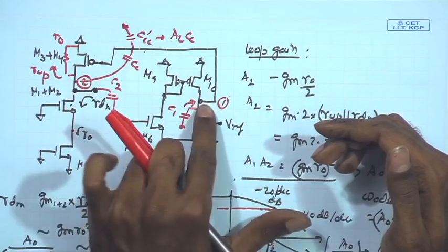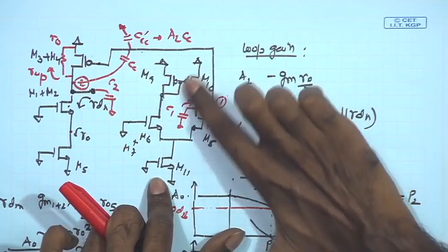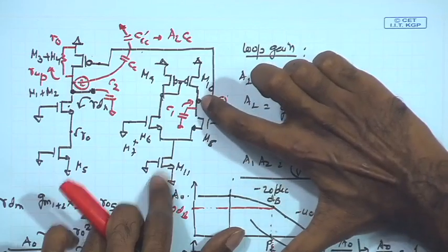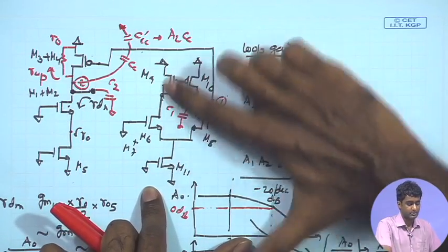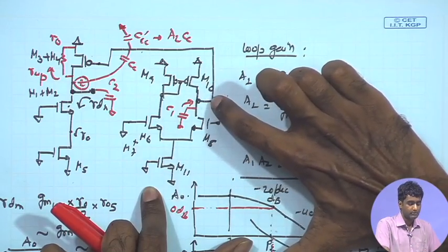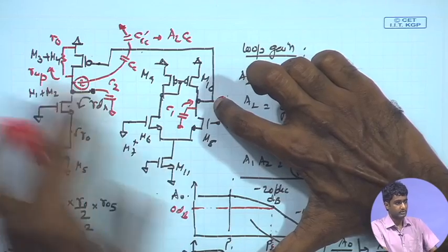For example, in this case, if you want to further improve the phase margin, you can try to make the impedance of the diff amp pretty high. If you make the RO of the diff amp pretty large by reducing the bias current and using a larger channel length, then the RO over here will also become large, and apart from CC you also have a significantly larger RO as compared to the main amplifier.